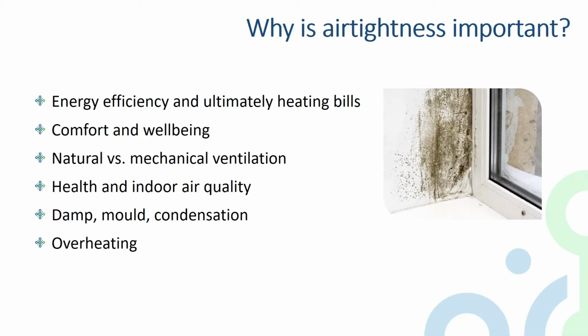By its very nature, it's air movement, so it's influencing both the comfort and well-being in our spaces. It plays an important role in influencing the ventilation strategy of the building as well, so it's an important balance to be struck between air tightness and the decision between mechanical or natural ventilation and subsequently how effective that will be in operation.